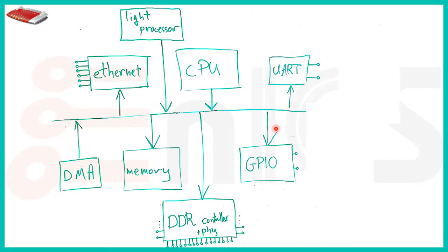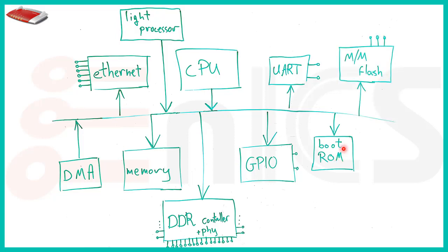So we now go back to our router and we're going to complete the whole picture to get a whole system on chip. We have our whole system that we discussed before with all of its parts, and now what we need is to add this BootROM, which is a special piece of code that's going to run when we start up the machine. And that's not enough because it's probably going to call a bootloader, which is going to be read from some sort of memory mapped flash. So we have to have a flash controller over here that's going to connect to our SD card or our piece of flash that's going to give us our application. And now we have really our entire router on this nice little whiteboard over here.